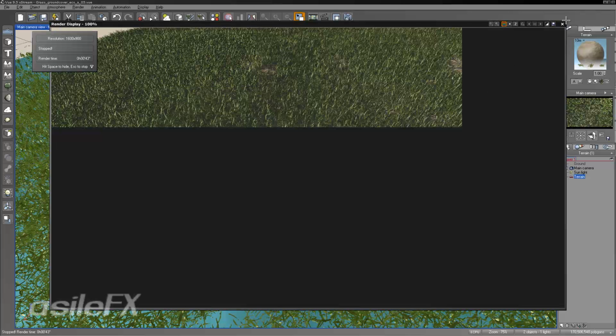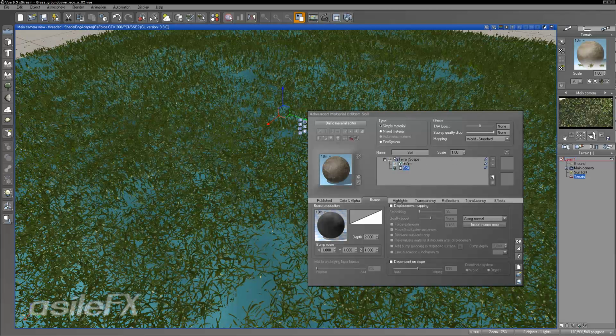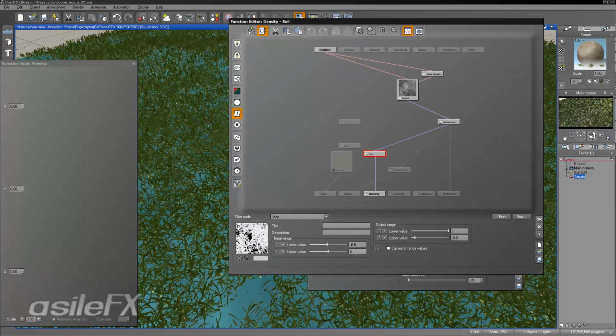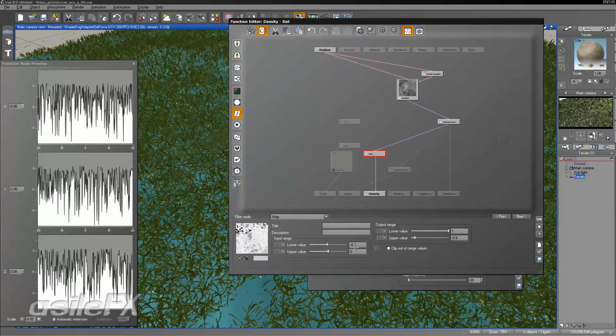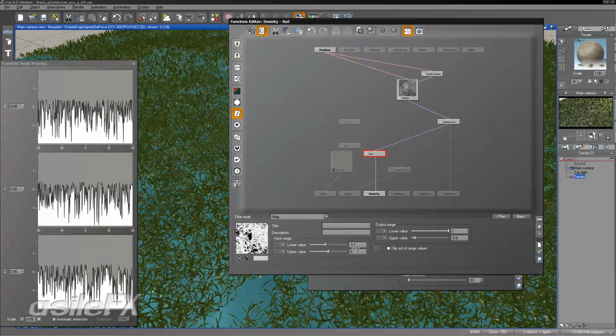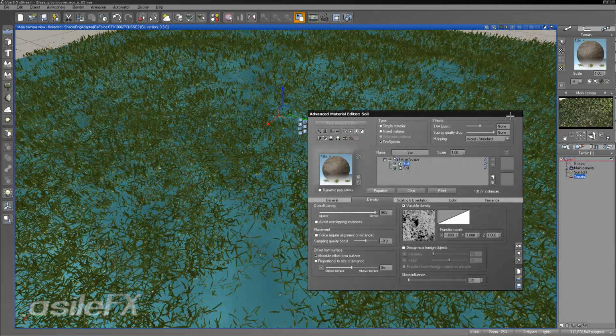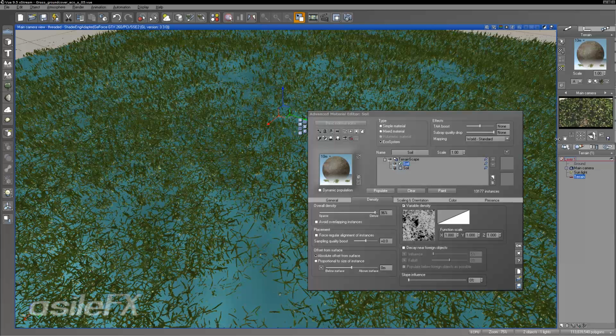And I just went ahead and canceled that because it looks like my presence or my density got a little messed up or it's too high. So what I'm going to do is set that lower value to 1.5. And see if we can't thin that out a little bit more.